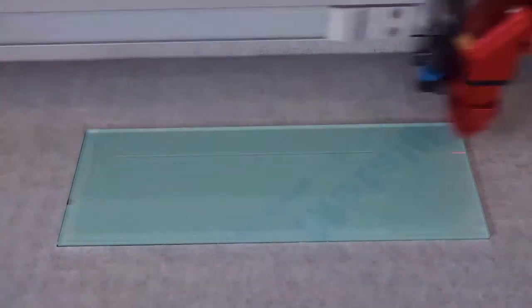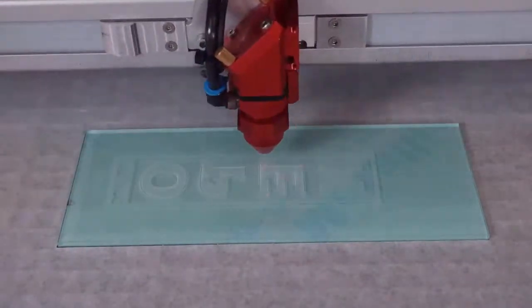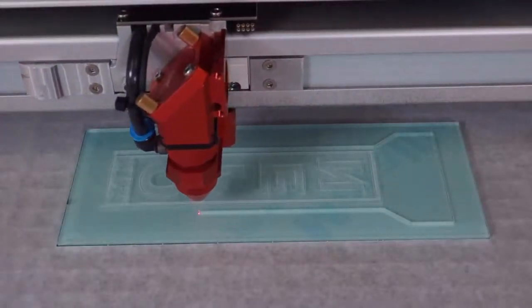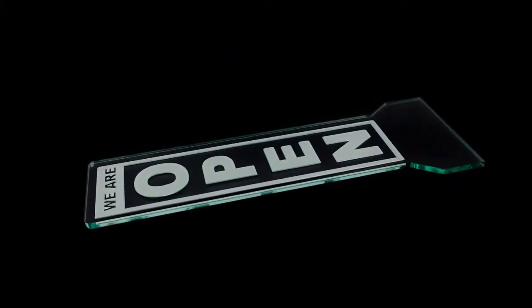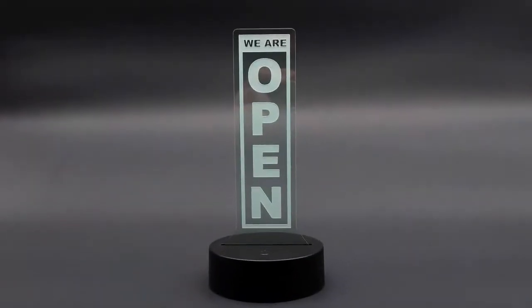So basically, I've taken the engraving. I just engrave directly into the acrylic. And when you distort the acrylic with the laser system, the benefit is when the light transmits through it, it actually causes those letters to glow. I run a vector outline around it, which really kind of makes it pop, and then take it out of the laser. And this is what it looks like directly out of the laser, and then into a light base.